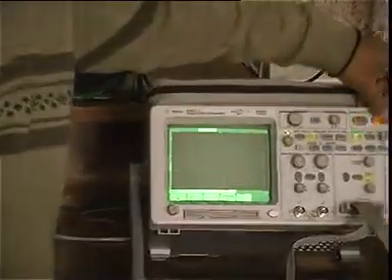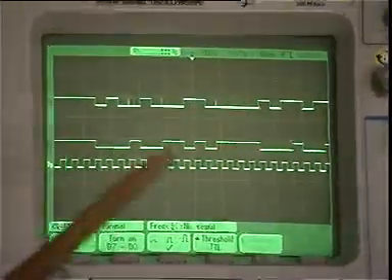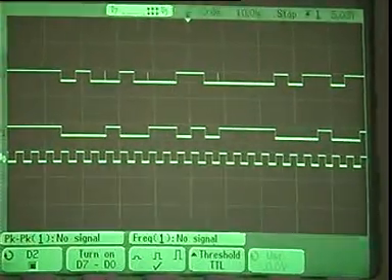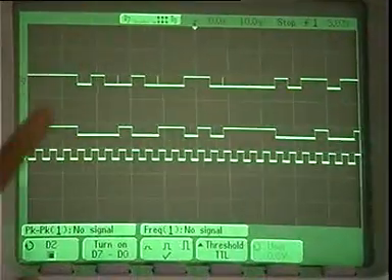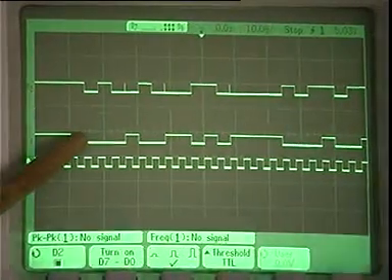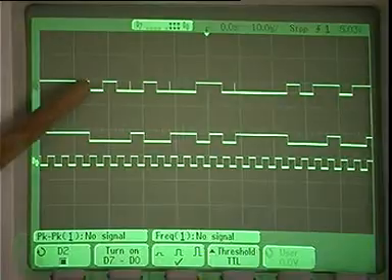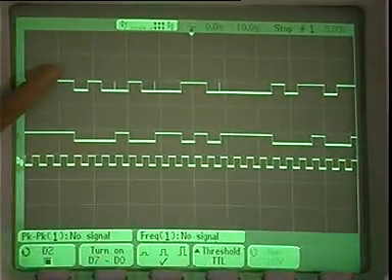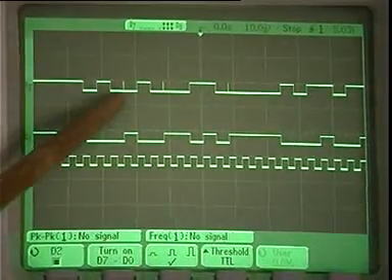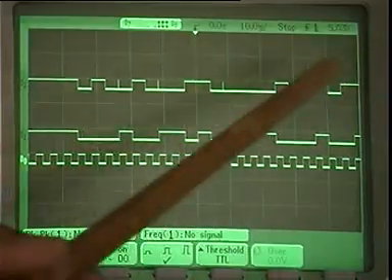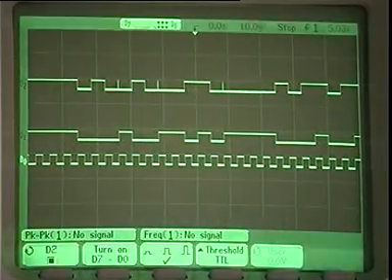Next, NRZS. Similar to what I told you earlier, wherever there is a 0 encountered in the data string, there will be a transition from low state to high state or high state to low state. Here, there is a string of about 3 zeros, so there are transitions from high state to low state to high state to low state, corresponding to the 3 zeros in the data. Likewise, you will transmit the NRZS waveform.